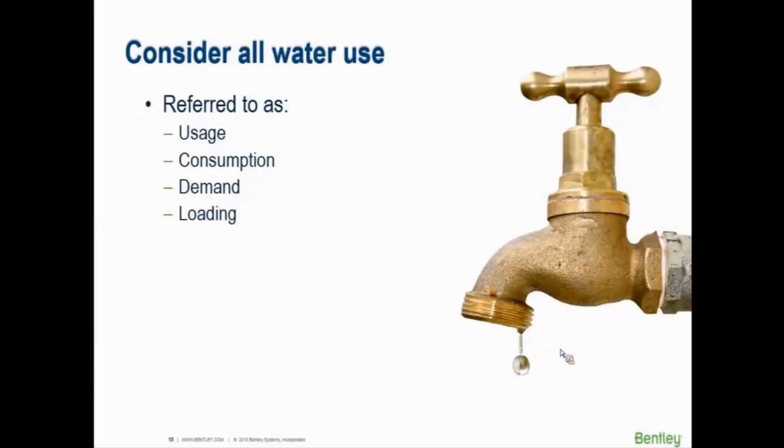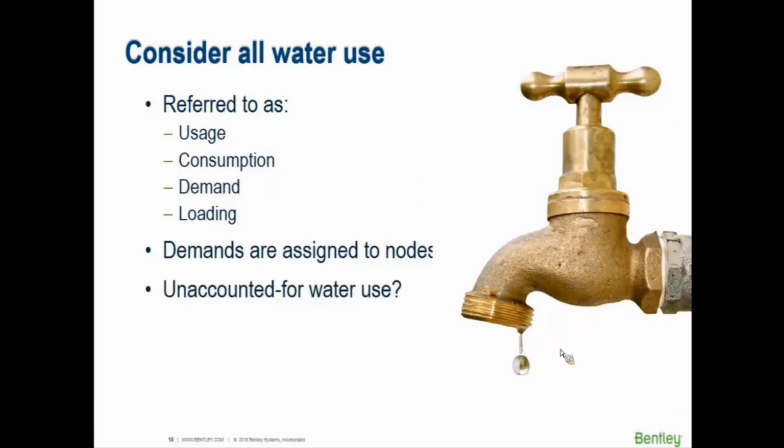When you do this, you need to consider all of the use of the water, meaning how much flow do they use, but then also unaccounted for water. A lot of times you'll see this, municipalities don't meter themselves sometimes, so you have flow going to irrigation, pretty significant amounts going somewhere that aren't metered. Hydrant flushing, maybe that's not properly recorded. It should be, but it's not properly recorded sometimes. Meters that aren't functioning properly, maybe it's such a low flow on the residential side, there's a leak that the meter's not even moving. That's a possible one.